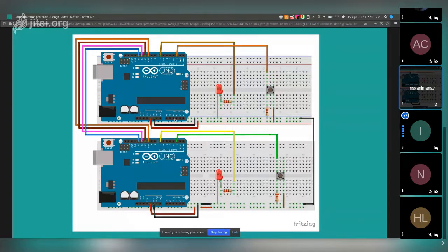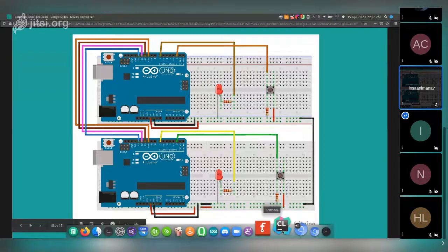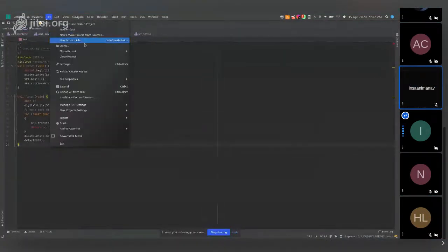To rectify that, we have interrupts. What an interrupt does is, the microcontroller keeps on doing its thing, and as soon as button 2 is pressed, whatever the MCU was doing, it stops in the middle, and whatever has been programmed for button 2 is executed. So the code in this case for button 2 is also known as an interrupt subroutine, or ISR, which means whatever will happen when button 2 is pressed is programmed into that. So now let's talk about how SPI is implemented.